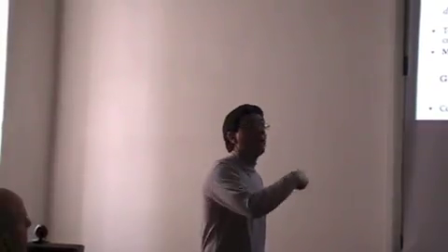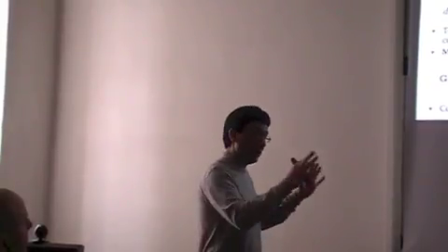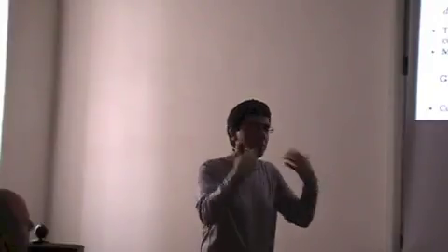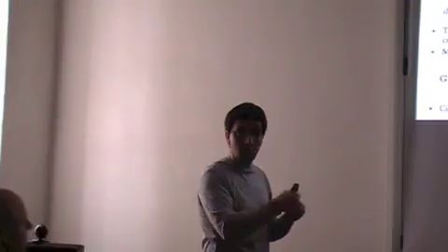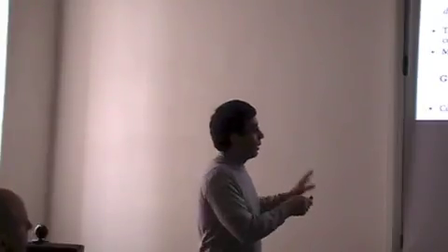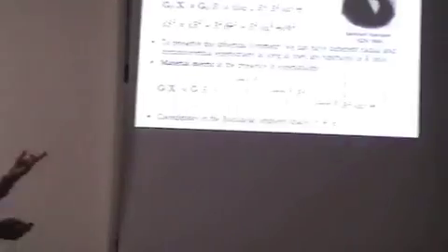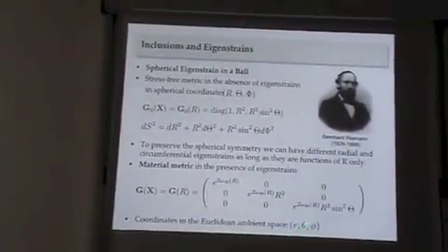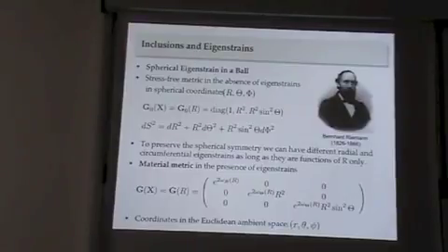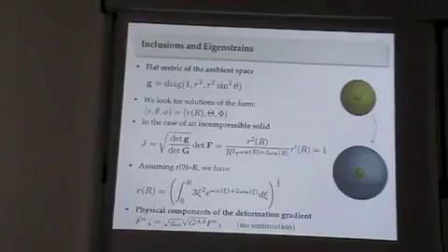And then of course the motion. So you have this, and when I say I put it in R3, it means I'm looking at a map from this manifold to the Euclidean space. So now in the ambient space, this is my deformation map, I have little r, theta, and phi. Now this is the classical nonlinear elasticity problem. Because it's so symmetric, first of all, this is the metric of the ambient space.